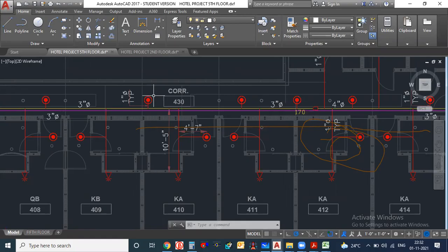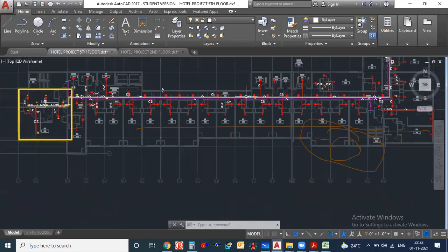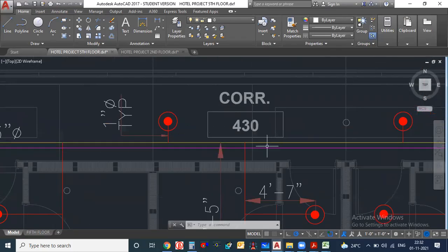That's why, whenever we do the shop drawing, we have to do the calculation once again, because if the contractor changes the layout, you obviously have to redo the calculation. This calculation you do according to your drawing, but the site condition may be something different. And don't bother about pipes being very close to each other, the installation team will take care of that on site.